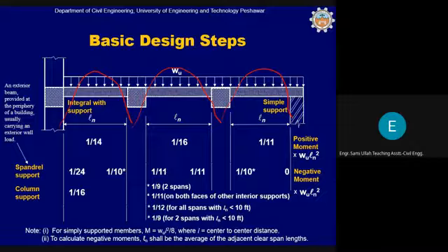Okay, Yasser? So there is a positive bending moment somewhere at the midspan, here at this location, and then we have negative bending moment at the supports here in this location. So the normal bending moment diagram for a continuous beam is basically a negative, positive bending moment combination in this manner, provided that the beam is subjected to uniform distributed load, just like this case.